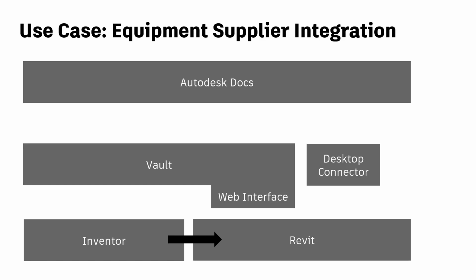Next, we'll look at how we can get this Revit model into the cloud. We have many ways to do so depending on preference, technology stack, and company setup. One way is to sync Vault with ACC, which means we need to load the Revit model into Vault. This can be done manually from within Revit or through the Factory Design Utility, which allows us to generate and upload a Revit file directly from Inventor into Vault.